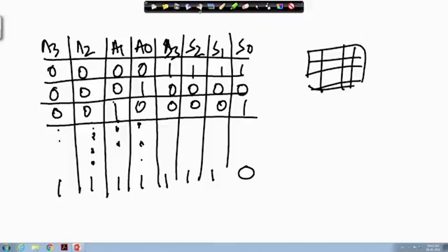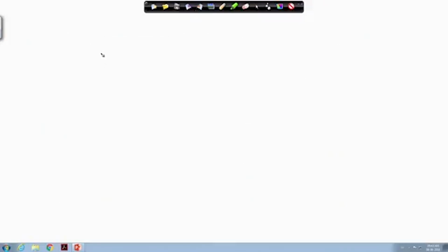In the incrementer design, what we have done is fix one input bit to 0 0 0 1. In the decrementer, the same thing: if I add 15 instead of 1, as I am considering 4 bits here, it will work the same as the decrementer design.